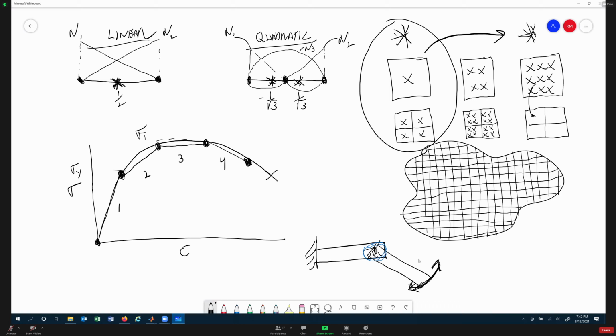So it's one of these things that people look at this whole idea around finite element analysis and the output of it, and they think that it's this ultra precision tool, and it's really not. It can be if you really know what you're doing and you really take care of the assumptions that you put into the model. But if you're sloppy, it can lead to really unsafe results as well, that you could make bad design decisions based on.